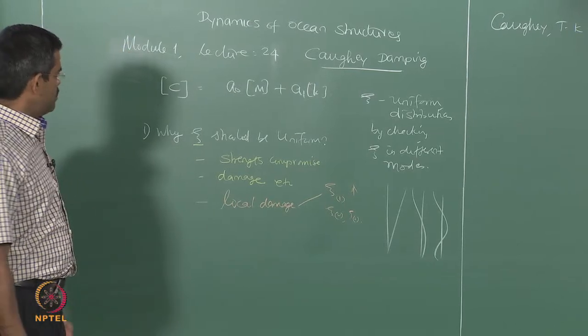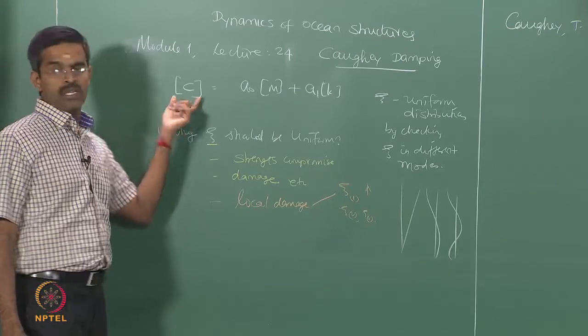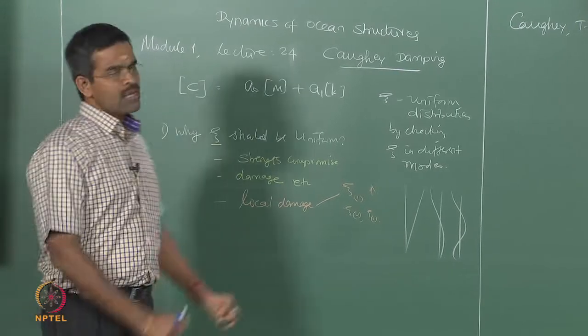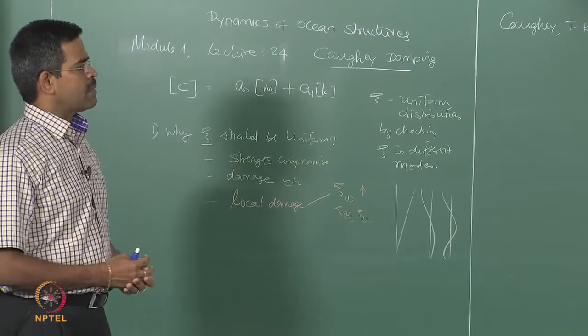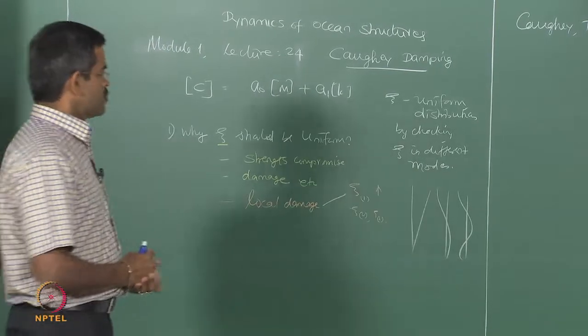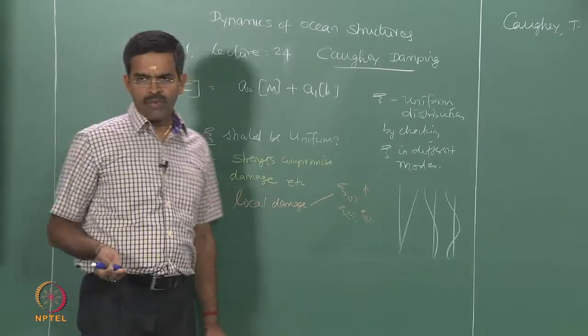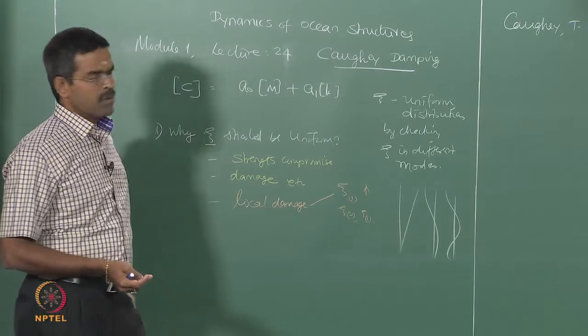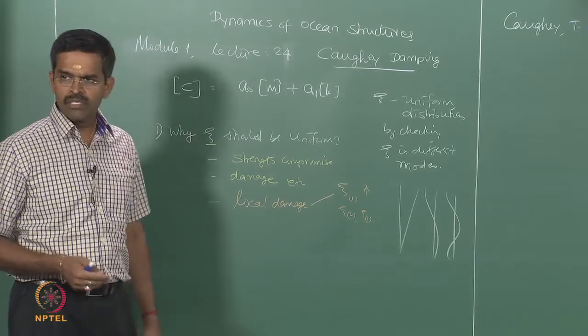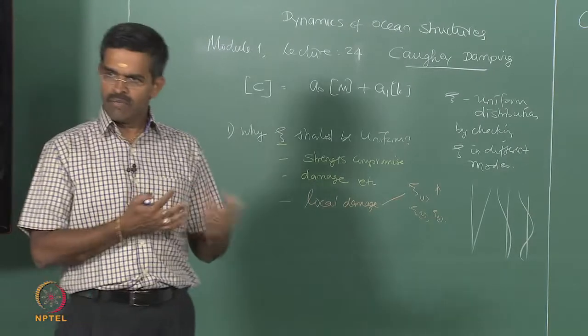Most importantly, estimating a damping matrix for a given dynamic analysis of a structural system where the new generation forms are involved. If you have a classical form of geometry, for example, a rectangular, rectilinear structure, curvilinear, shell shaped, etc., where the geometric forms are more or less predefined, there is absolutely no difficulty in using the classical damping model, because there is always a uniform distribution of mass for the entire structural system, because that is how the system is generally evolved.